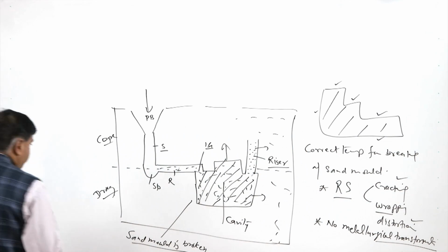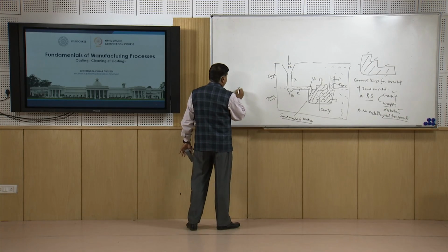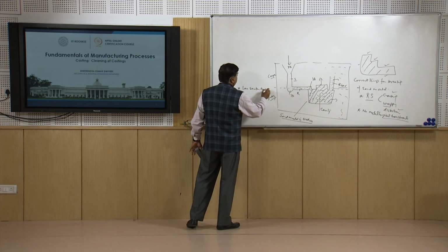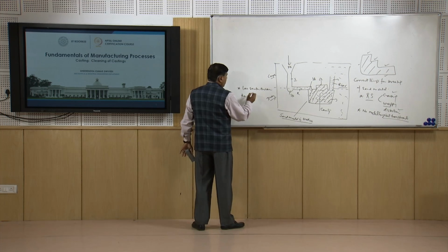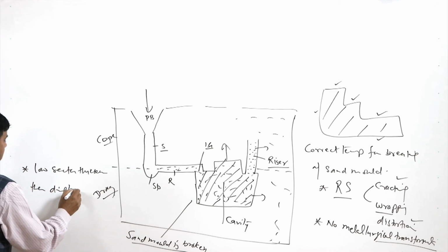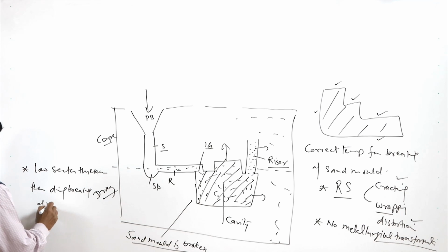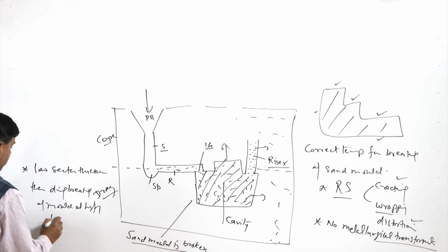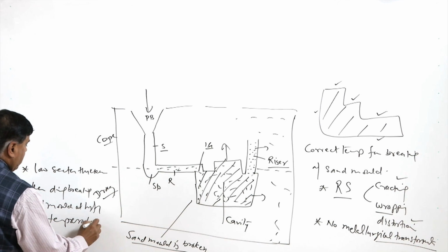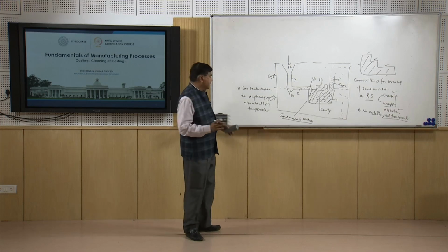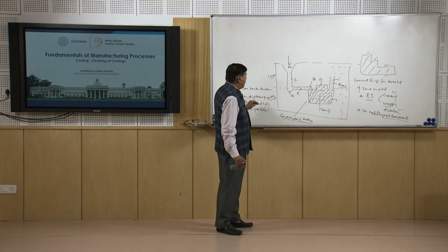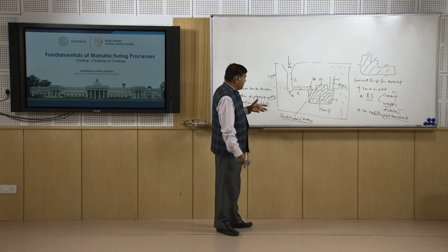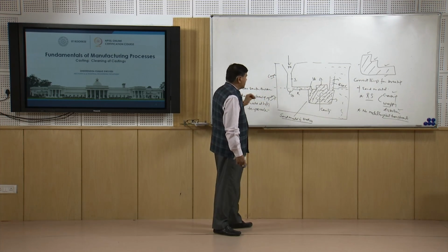Further, if the casting is of very low section thickness, then breaking of the mold at high temperature can lead to the fracture of some of the sections, because at high temperature of the casting, if the mold is broken, then the thin sections of the casting may not be able to support the forces acting onto the casting during the breaking.